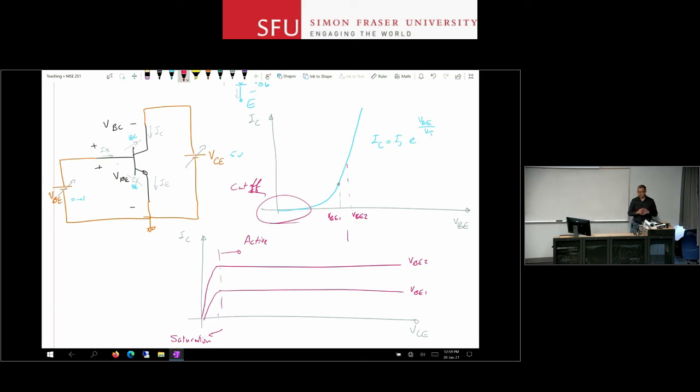In analog electronics, I would say 98-99% of the cases, you keep the device in active region. You still use cutoff and saturation from time to time for doing some special functions, but in the vast majority of the cases, your device is in active region. And that is going to be our introduction to BJTs. That's the lecture here.